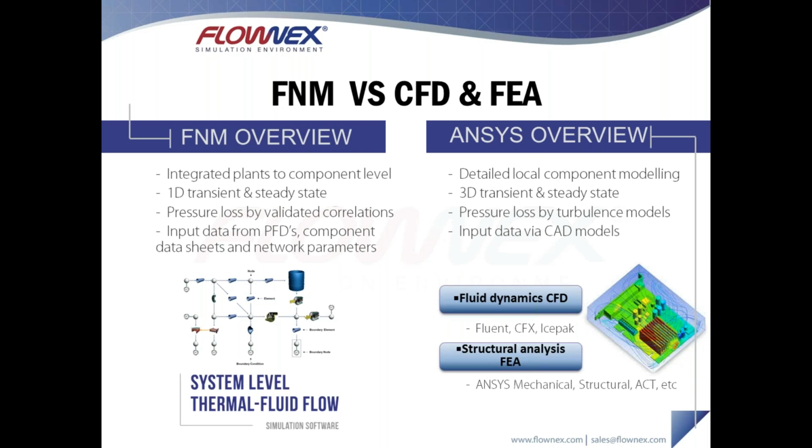inside of the system. This type of modeling is based on semi-empirical models for the components themselves. So the models themselves are not done in the traditional sense of CFD with, say, a turbulence model. Instead, we have the characteristics of the flow inside of the components modeled using empirical correlations. So, for example, the frictional losses in a pipe are accounted for using Darcy-Weisbach or Hazen-Williams instead of a k-epsilon model.